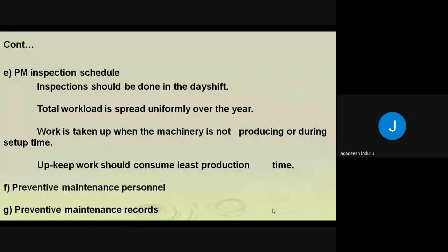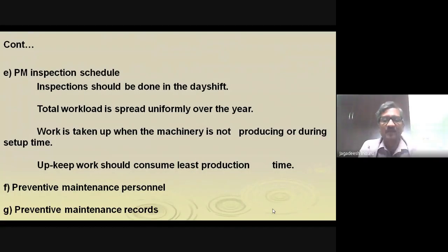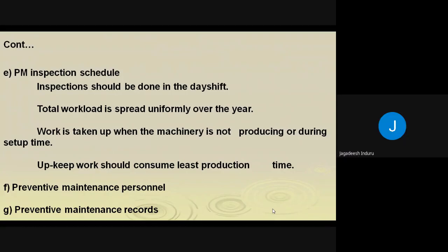Most of the times, we are going to have the plan in the day itself, and we are distributing what person and what work they are going to do. That is actually making a smooth flow of your program. Preventive maintenance personnel we need to decide critically depending upon their education, experience and skill. And we need to maintain the preventive maintenance records, because what part we have changed, what part is giving a noise, that will give the idea in a retrospective manner later.